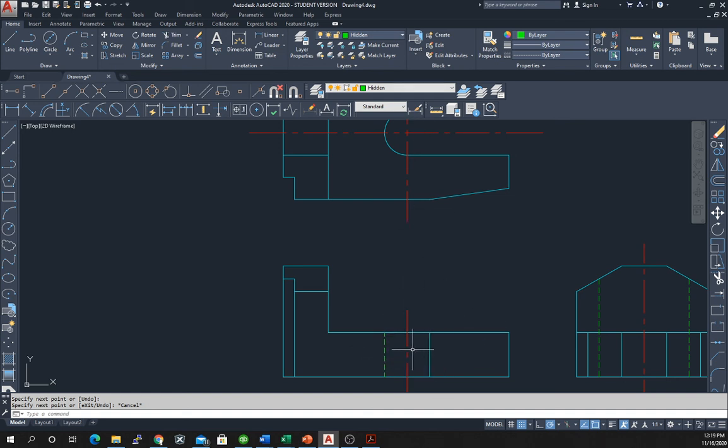So those are the three features on the side. We have this relief. So this says that there's something changing as you're looking at this edge. This says that there's a hole here. And then this says that this is the end of the hole. So if there were only a hole, and not a complete cutout, then we would actually have a green line there and a green line over here somewhere. But since we have a full cutout, then we only have this one hidden line over here.